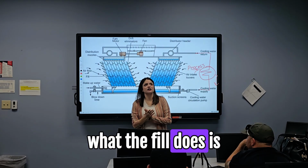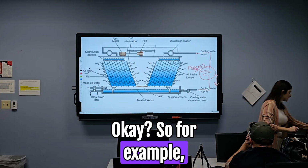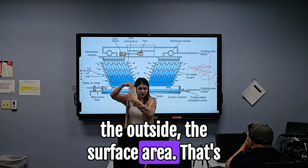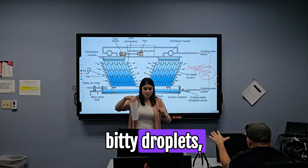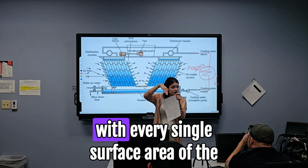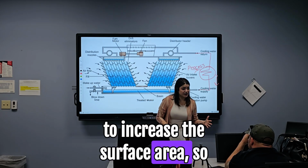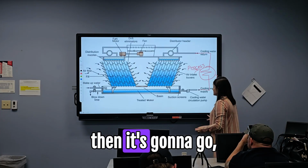What the fill does is break it up into small droplets to increase the surface area. So for example, if I have a stream of water coming out of your bathtub, the surface area on the outside is the only part that would be coming in contact with the air. Now, if we broke it up into small itty bitty droplets, and remember this is a 3D droplet, now the air can come in contact with every single surface of the droplets. So the fill breaks water up into small droplets to increase the surface area, so that we can have more efficient cooling. It's going to go down the fill, and then into your basin.